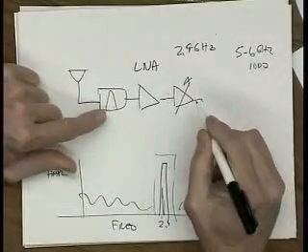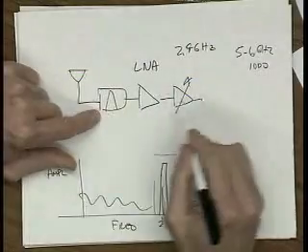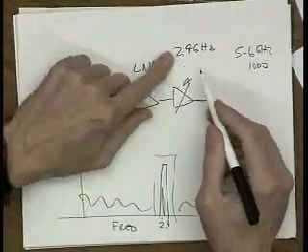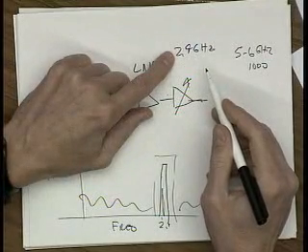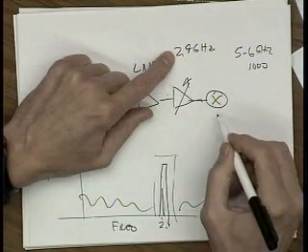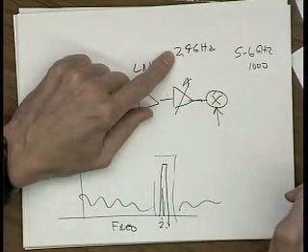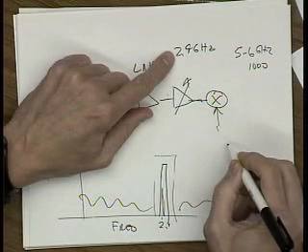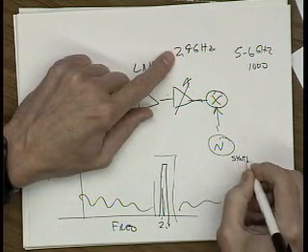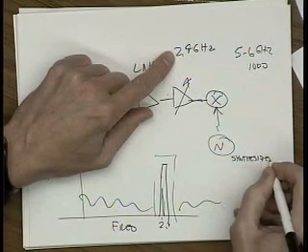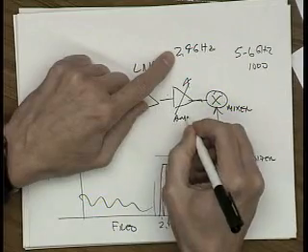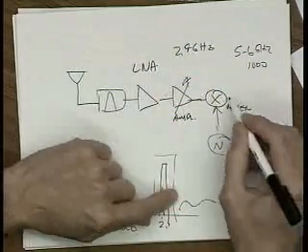Can't use feedback, obviously. These circuits are all open loop, like your second project was. You don't want to amplify any more at 2.4 gigahertz than you possibly can. So what you do then is you mix. You have a mixer. What a mixer is, it's just a multiplier. And the other circuit you have to have is a synthesizer. So this is the synthesizer, and this is the mixer. And these are amplifiers. So these are kind of the basic elements of a radio.